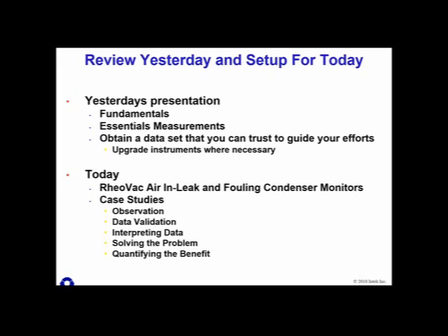Several people got back to us and they said that they have been battling high air-in leakage from various different sources or unknown sources. Another person said they're performing engineering evaluation in response to a dramatic increase in their cooling water inlet temperatures. So something environmental, or the configuration of their system or their cooling water source has changed. And now they're getting cooling water inlet temperatures that are much higher than the plant originally had, apparently.